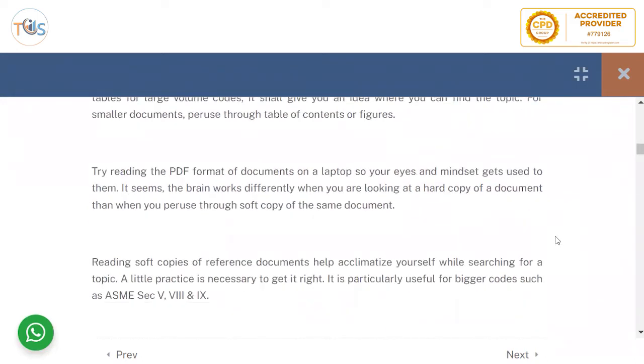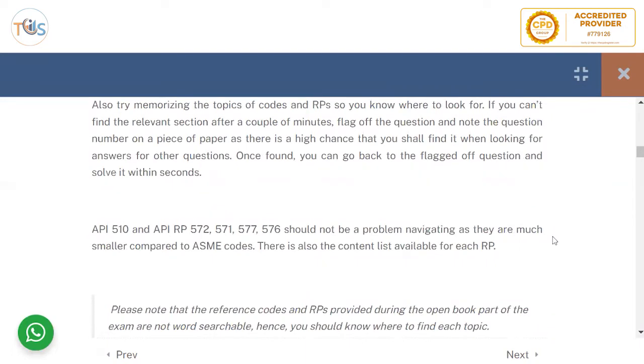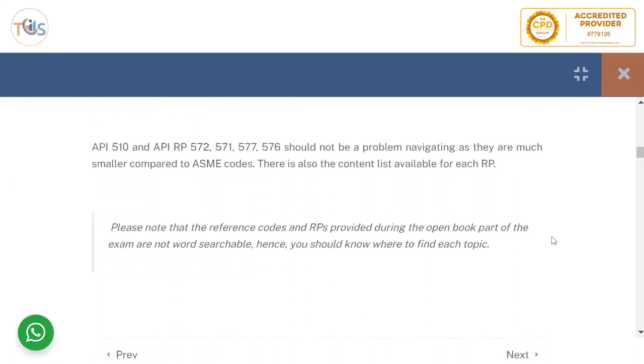And then the other thing is you always need to read the PDF document. Obviously nowadays nobody has a hard copy anyway, but you can highlight the PDF document, and your eyes get used to which page you can go to in ASME Section 9 to determine the qualification range, say for a pipe diameter or thickness, etc. So it's all about practice, flagging, tabbing, highlighting, and you get the hang of it. It's something you need to learn, how to use the codes and where to look.